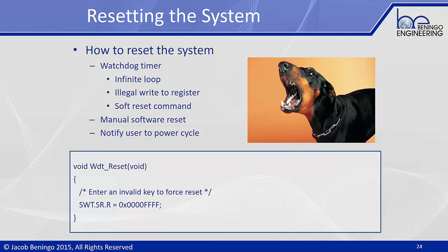There are some that offer you a hard reset option, which basically is powering off the microcontroller and powering it back on. You have to read through the data sheet in order to see what the capabilities are of your watchdog timer. A production intent bootloader isn't going to, at the end of the bootloading process, turn on a light or issue a message that it is now safe to restart the embedded system, and please do so now.